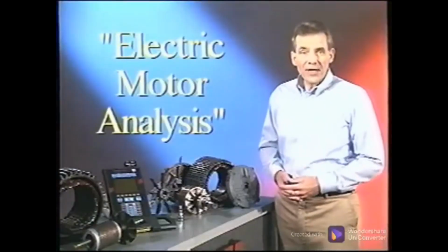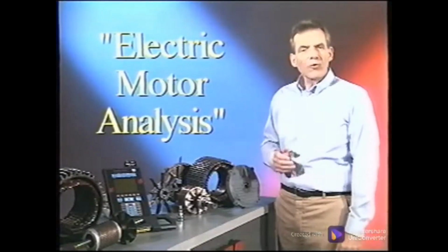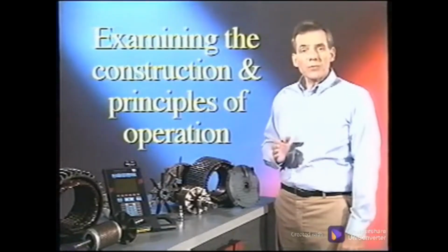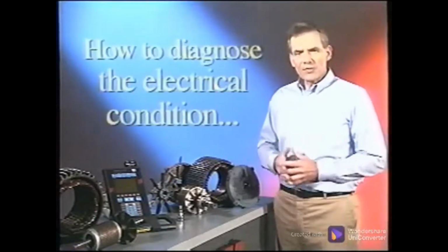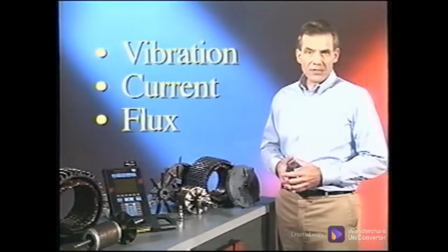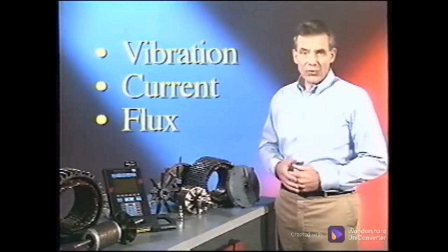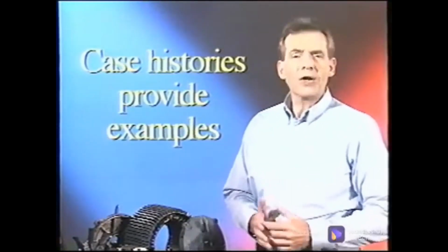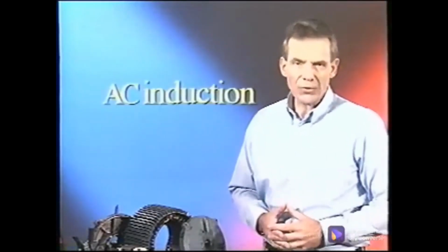This program, Electric Motor Analysis, provides a solid foundation for analyzing electric motors by examining the physical construction of motors and the principles on which they operate. Here we demonstrate how to diagnose the electrical condition using vibration measurements, current measurements, and flux measurements, including the best setup for each. Case histories provide examples of all the measurements with specific instructions on how to determine the motor condition. Although we illustrate the physical construction of DC and synchronous AC motors, this program focuses on AC induction motors.